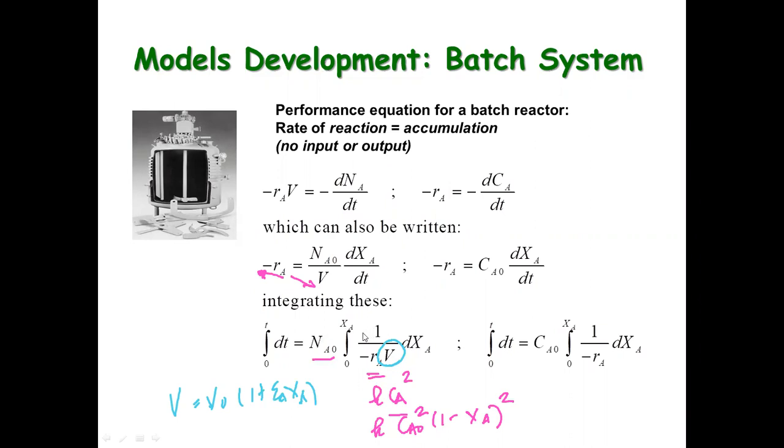Because if your reaction is liquid phase inside the batch reactor class, there's no need for you to write it after the integral sign. It can be written before the integral sign because volume for liquid phase reaction is always constant. But in the case of gaseous reaction, it can be constant, but most of the time it's not constant. So for it to be safe, always write it after the integral sign. Anyhow, if you have realized that this one is liquid phase, I might as well transfer it before. Because it's a constant, you will see that it's a constant. So you can write it before.